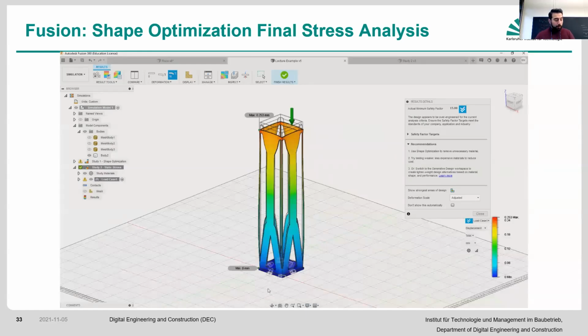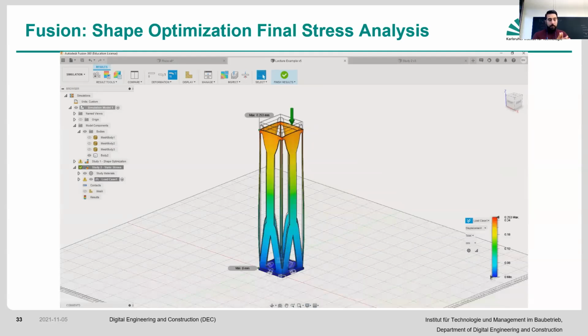So your objective based on the term project is that this platform and this column should not displace more than 3 millimeters. If it does displace more than 3 millimeters, you have to go back and change some of those aspects of it, maybe shred a bit less, or maybe change your material properties. You have to use the proper, correct material property.